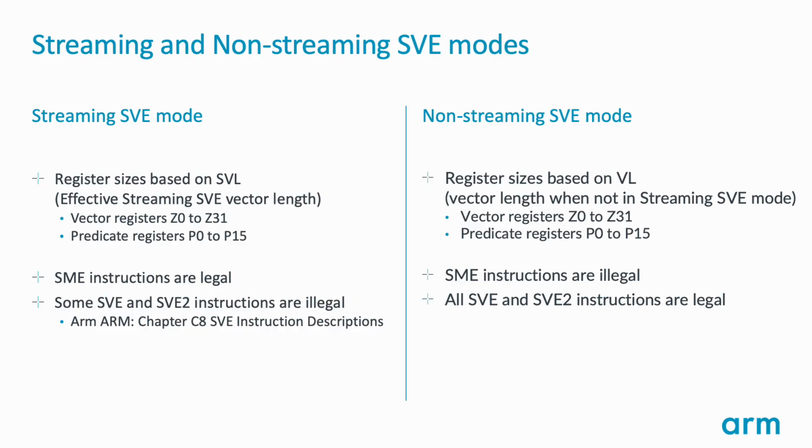Okay. Basically, we are trying to give a difference between what is a streaming SVE mode and what is available in streaming SVE mode. Streaming SVE mode enables execution of SME instructions. SME instructions provide high performance benefit for matrix data computation and vector data computation, and the different predicate mechanisms available in SME architecture enable building simple control flows for executing matrix-based computation, matrix data processing and vector data processing.